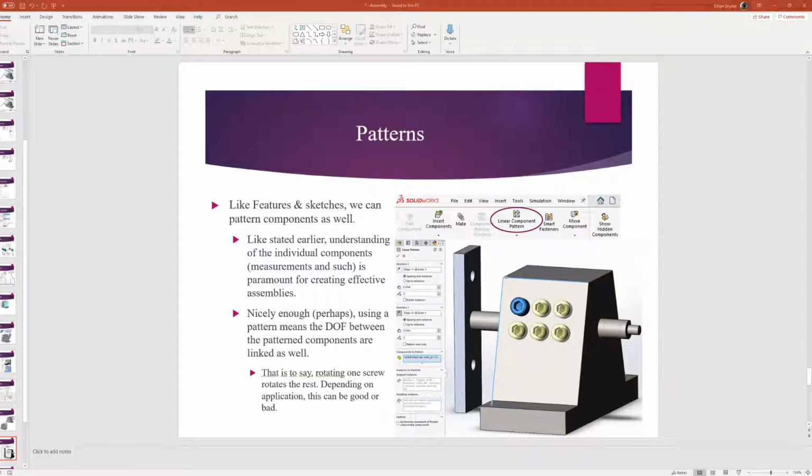Just like what we want to pattern, or rather mirror, these features here. I'm going to open the little drop down so I can see everything, since this is taking up my feature tree. It asks me for a plane to mirror this across. I'm going to select the one that I just made, and select the local pattern as the component.